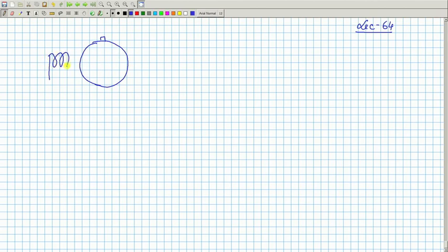which is represented like this here, and this is the flux per pole created by the machine when you pass some current IF here, and we considered generator mode of operation, and suppose it was running in this direction with a speed n, then this side is north pole, this side is south pole. So, what I am trying to tell in this schematic diagram, you must try to understand that whatever is happening in the armature conductors under a pair of poles, the same thing is going to happen to other armature conductors under the next pair of poles.